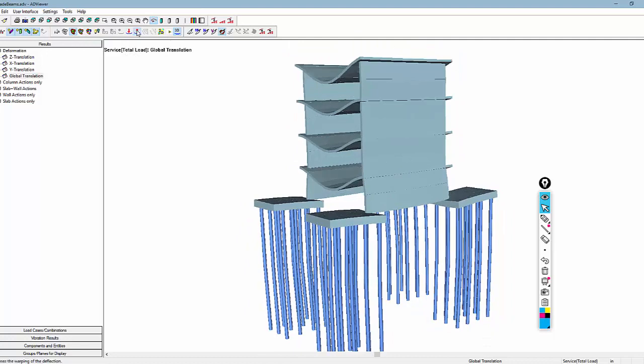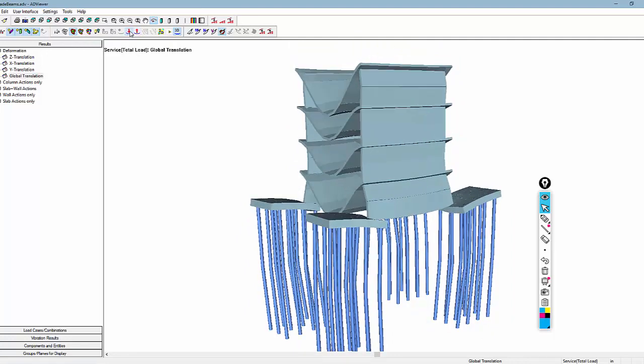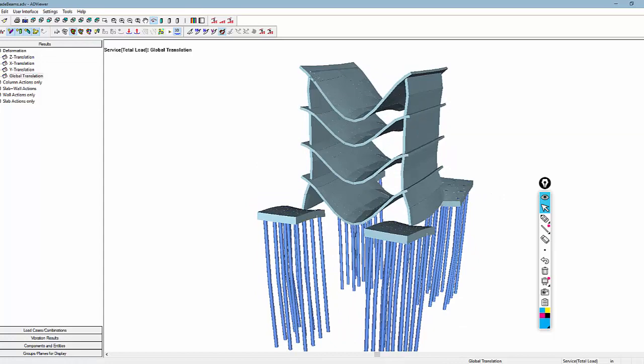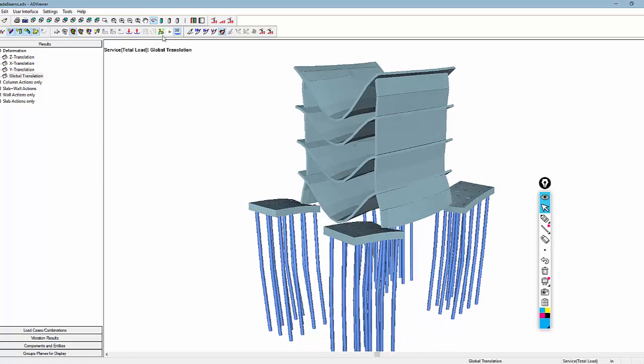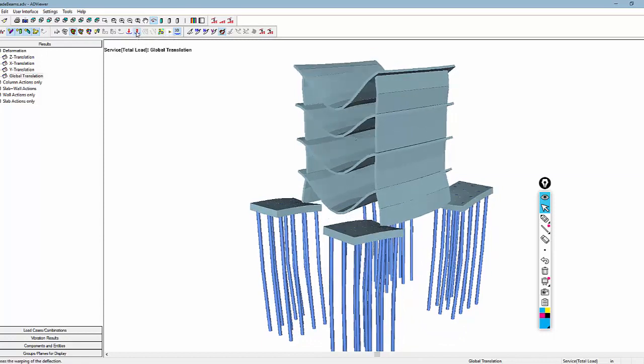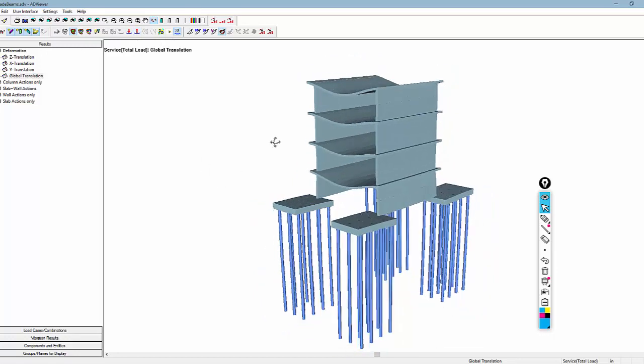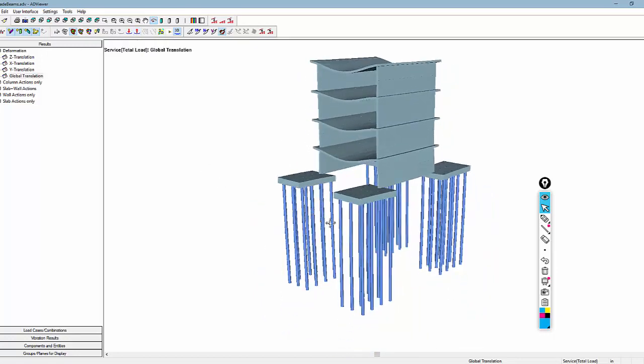If we amplify this, you can see that a little more clearly. So here we just get severe deflection in those slabs. But that's fine. This is just for investigation's sake. So once that's done, we can now use these results mainly to determine capacity, whether or not we have axial forces in these piles that might exceed their bearing capacity, or also the bearing plus potentially skin friction for the pile, and also just actions in the pile caps based on the way that this is built.